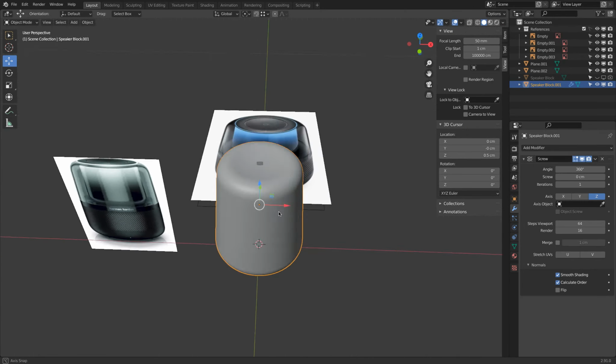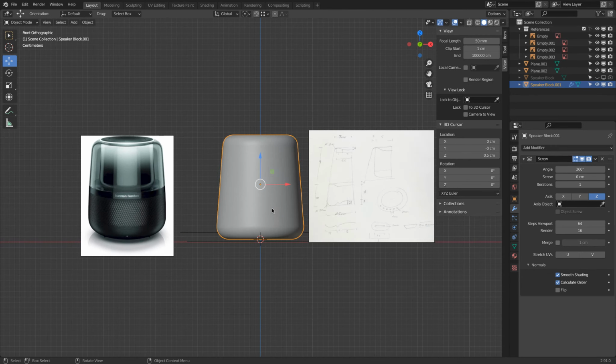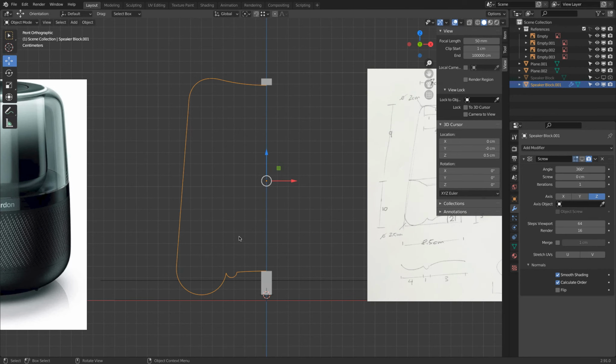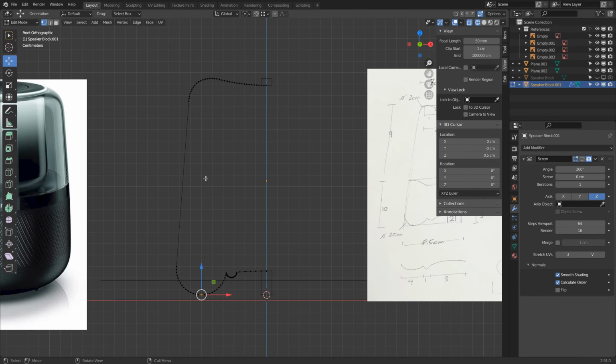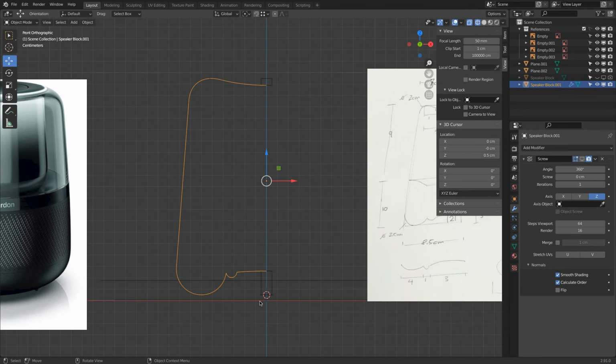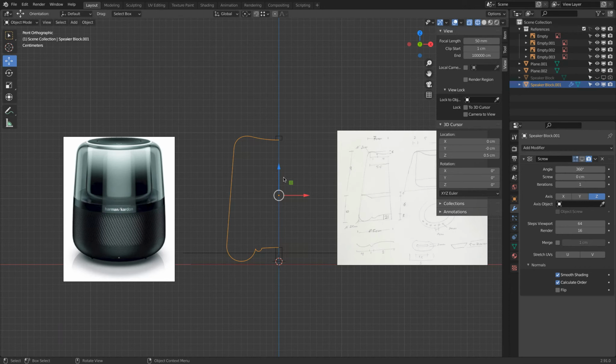Okay, very nice. So some very basic mesh modeling using vertex, bevel, and then working with the 3D cursor and adding the circle and moving everything, vertex counting to then create nice and smooth transitions so that we then can take this and create a revolve object. And then in the next video, we will add some of the interior details.